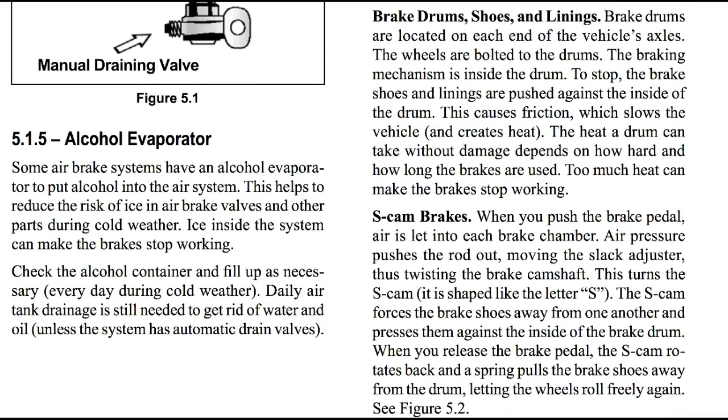Brake drums, shoes, and linings. Brake drums are located on each end of the vehicle's axles. The wheels are bolted to the drums. The braking mechanism is inside the drum. To stop, the brake shoes and linings are pushed against the inside of the drum. This causes friction, which slows the vehicle down. The heat a drum can take without damage depends on how hard and how long the brakes are used. Remember, too much heat can make the brakes stop working.